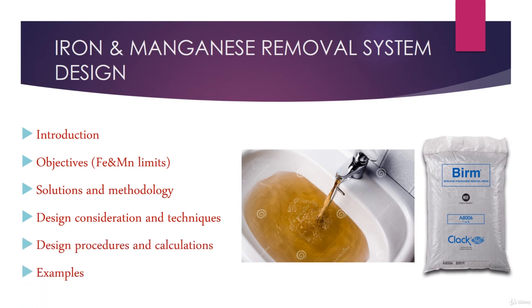Finally, we will learn how to design pearl and green sand filters in terms of the amount of media, the specifications of the vessel and its dimensions, the diameter of the vessel and the depth of the media layers, and the specifications of the control system and the distributors.